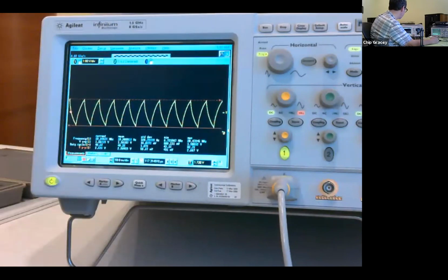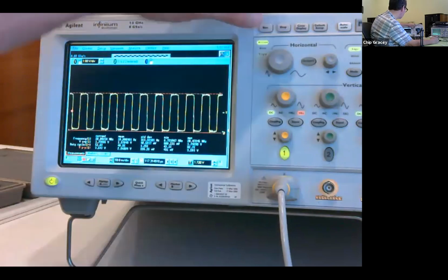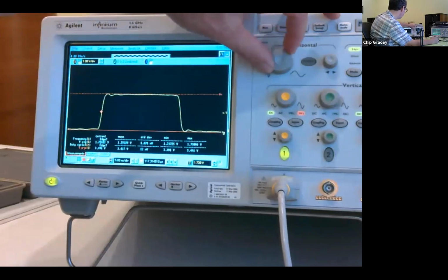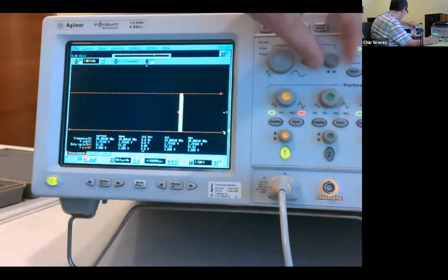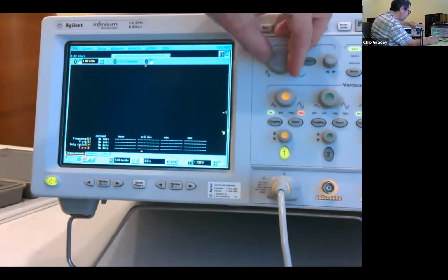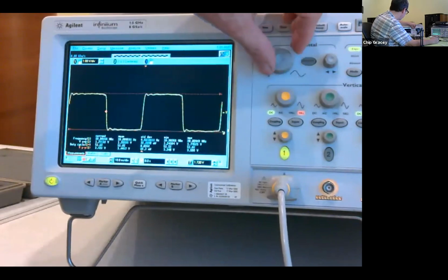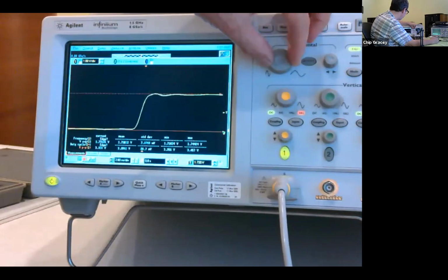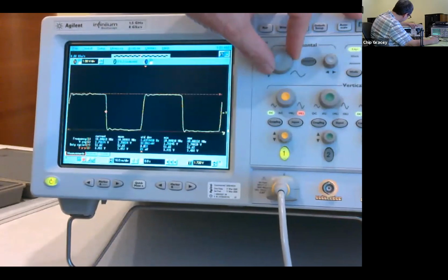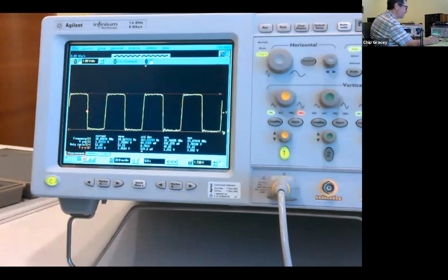And then this is the important one, that shows what the chip is seeing. Let me get rid of all this trigger offset, go to 0. Here's 1 nanosecond per division. It's about 1.5 nanoseconds rise time and fall. So this gets us around that jitter problem.